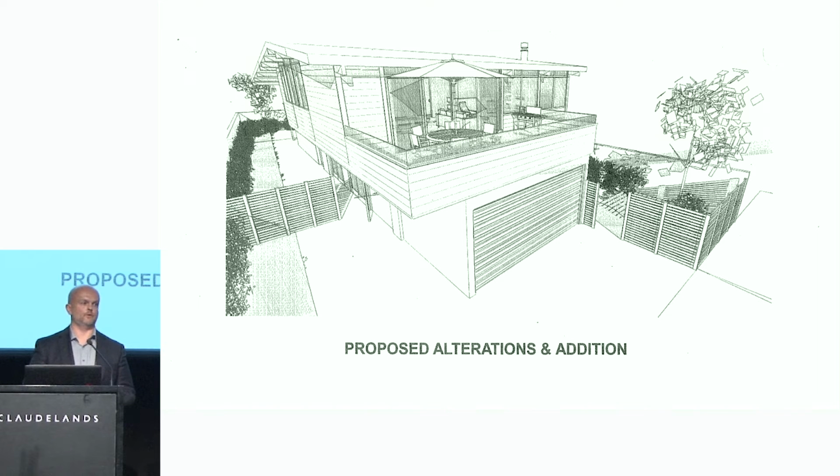A picture tells a thousand words, and so this is a house that I cycle past. Just looking at it, some of the things that we could say, okay, well, it's going to need a bit of a frame at the front there, possibly a soft story, and it looks like you've got some block work and level ground and so on, lightweight roof, lightweight framing at the top. Straight away you can see this, and it doesn't take too much effort just to get a snip of the architecturals and put those in.